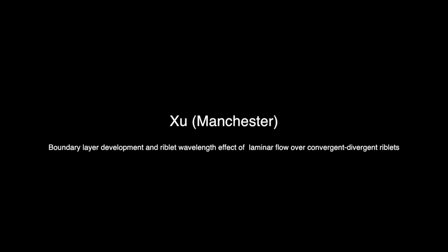So I just gave the conclusion. Our experiment is the first experiment that proves this surface texture can induce Prandtl's first kind of secondary flow. I have argued that Prandtl's first kind of secondary flow can occur in both laminar and turbulent boundary layers. Our case is laminar. But Prandtl's second kind of secondary flow, we just call it second kind, can only occur in turbulent boundary layers or turbulent flow fields.